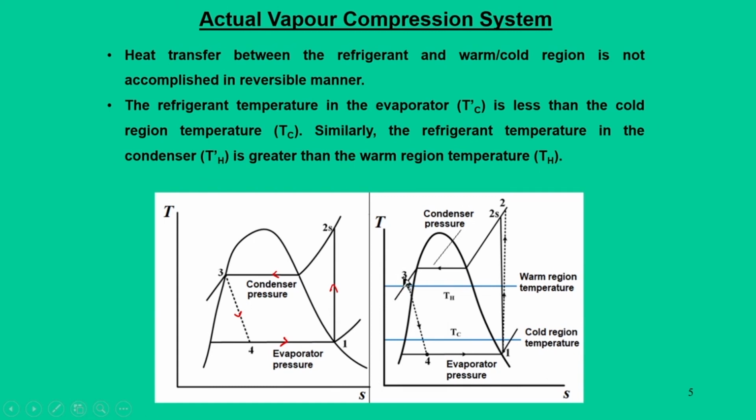This is basically done just to enhance the refrigerating effect, because point 4 will be accordingly located slightly differently on this diagram, so the evaporator load also increases.